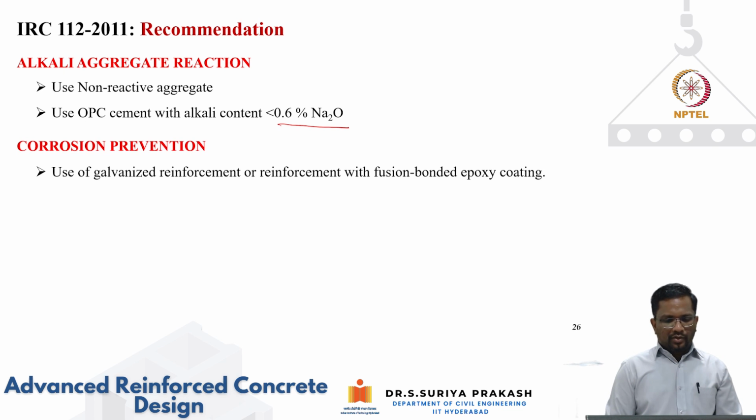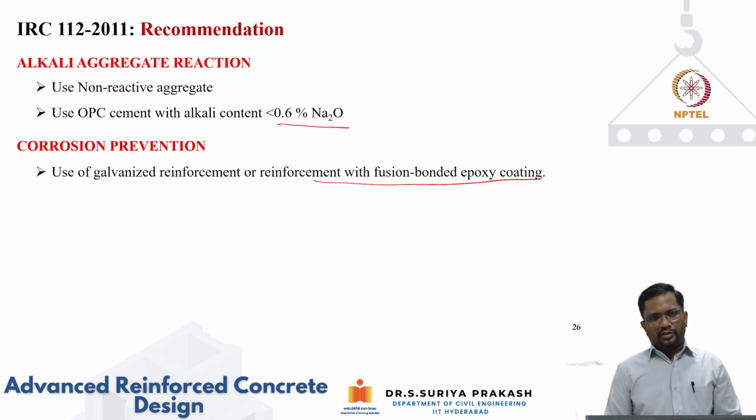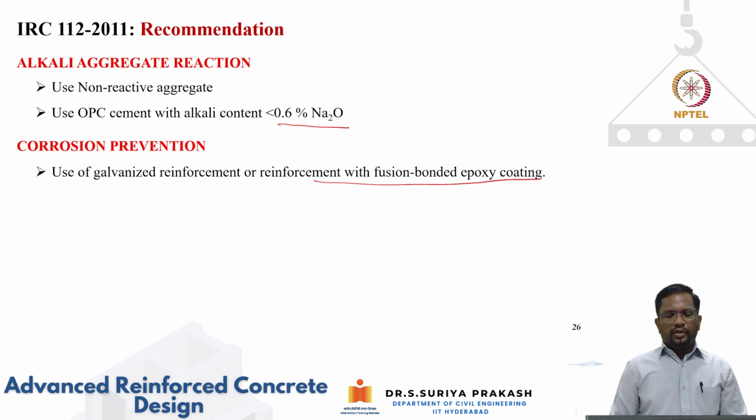And for corrosion prevention, IRC provisions recommend using galvanized reinforcement or reinforcement with fusion bonded epoxy coating. When your elements are subjected to a high amount of corrosion, chloride ingress or CO2, they are recommended to use galvanized reinforcement or reinforcement with fusion bonded epoxy coating.